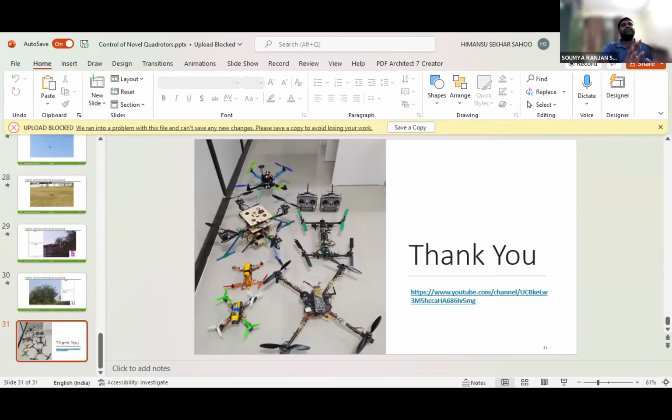So the vision here was usually during obstacle avoidance with conventional vehicles where the position and attitude are coupled, you have to plan both the position and attitude for obstacle avoidance in very thin scenarios. But here you need not couple them. So you just plan your position, and the attitude gets determined depending on the width of the gap between the obstacles. So you can plan them completely independent of each other. Okay.